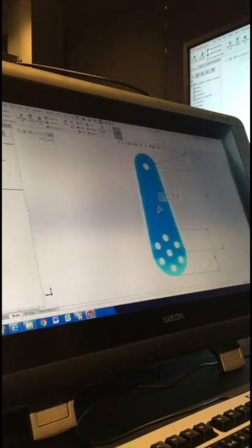One of the tools SolidWorks has built in is called Instant 3D. I've gone back to this part to show you how it works. When I click on this face, I've just selected the face. That face is part of that boss extrude, which you can see highlighted in the feature tree. The dimensions we have in the sketch of the boss extrude are what's showing here: the 30, the 45, and the 90.